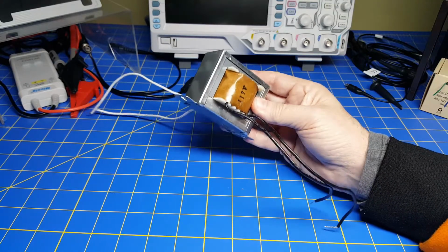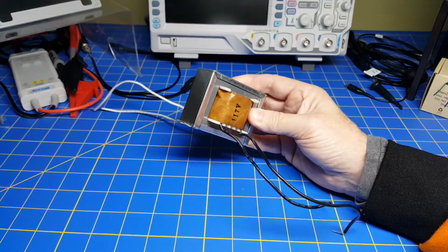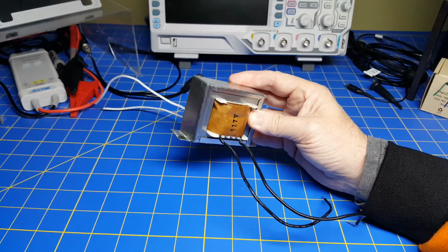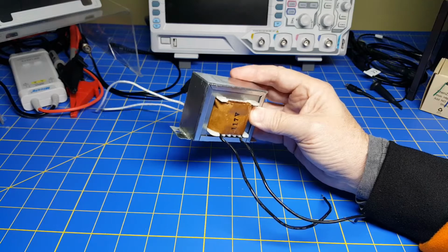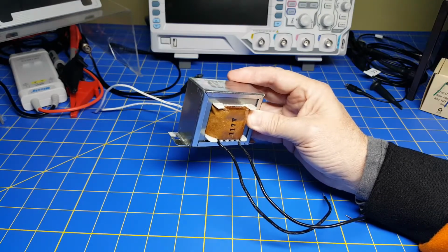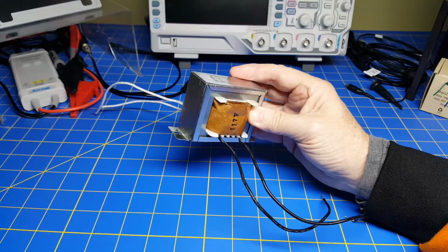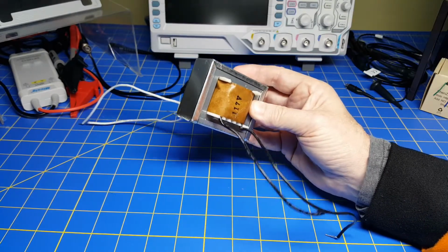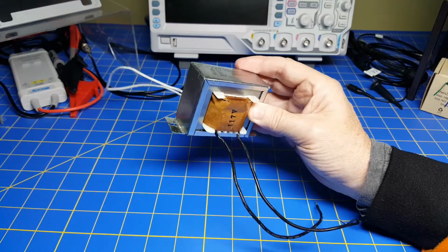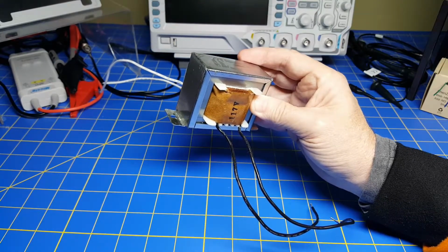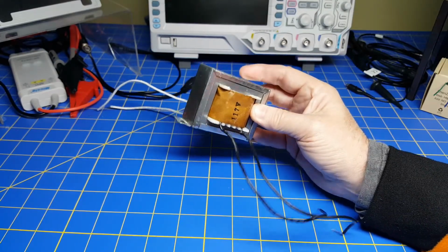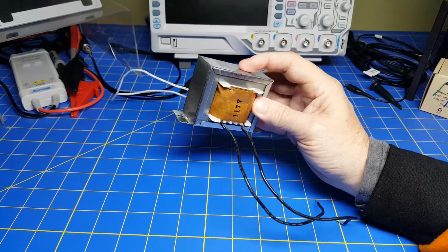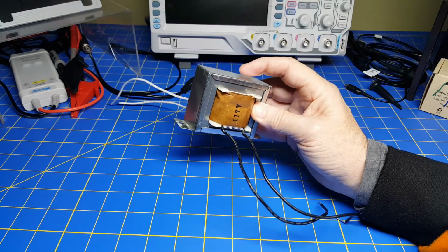So it's very important, before you build a model for something like this or any piece of equipment, that you define the operating range that you're going to be modeling. For example, as we showed in the previous video, if I'm going to be applying higher than rated voltage, I then need to consider the nonlinear characteristics of this. But if I apply only rated voltage, I don't have to worry about modeling all of that complexity.